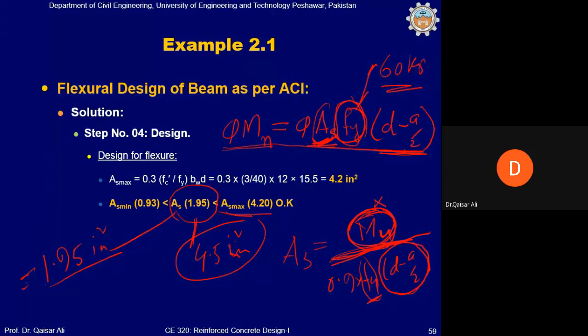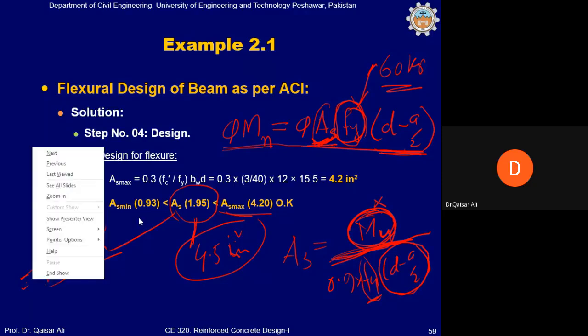And the width of the beam is 12 inch. So if you try using number 4 bar, you will probably require 2 layers of reinforcement or 3 layers of reinforcement. Let me demonstrate this to you. Because this is your first problem, we will learn how we select the bar to be placed inside the beam. This is the stirrup, and this is the available space.